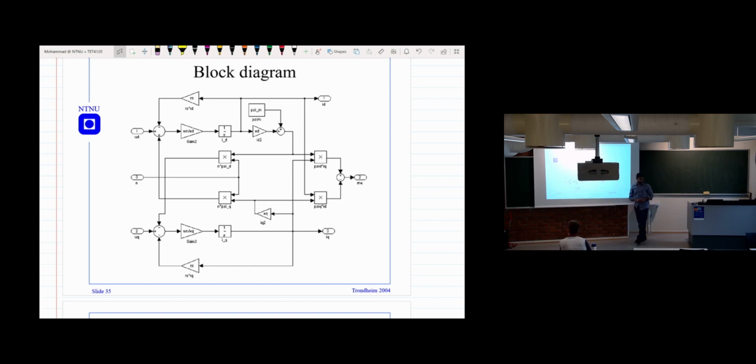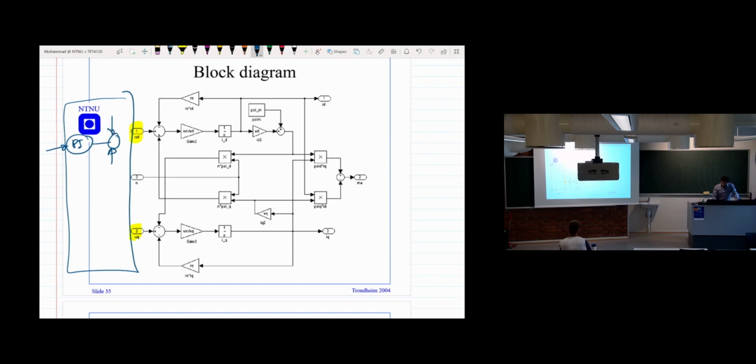If you have the dynamic representation, then you have the dynamic model in the block diagram. So you have this Ud here, and you have the Uq, and here we implement the control part. This is the controller that we implement, like one PI controller for the current reference, and some cross-coupling terms and some feed-forward terms that give us the Ud control signal.